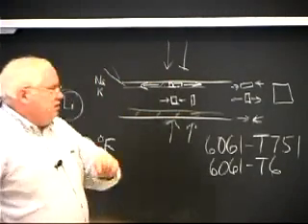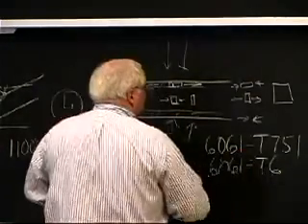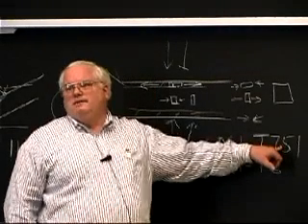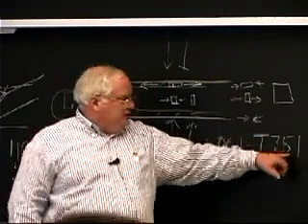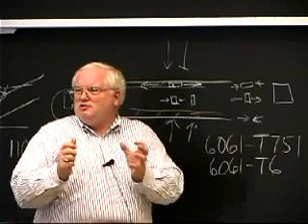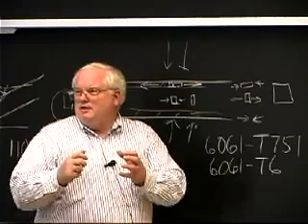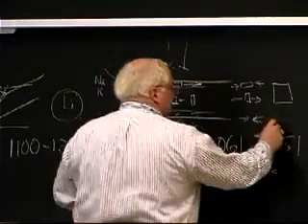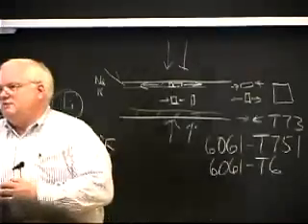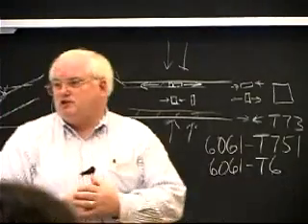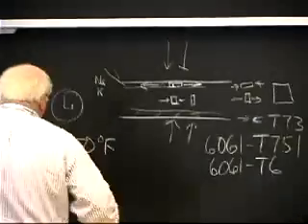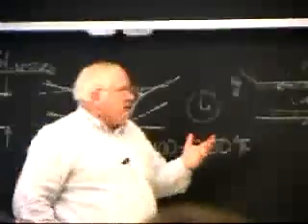That washer was supposed to be, I don't remember, 6061. They had on the drawing T751, but in fact, how do you stretch a washer in the axial direction? How do you grab it? There's something else called T73, and the 3 means that you squeeze it 3%. You compress it 3% to stress relieve it, which is what they should have done with the washer, but they didn't do either one. That's why it had residual stresses, that's why it cracked.